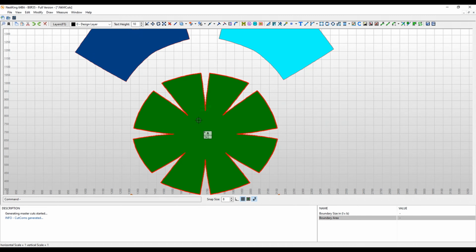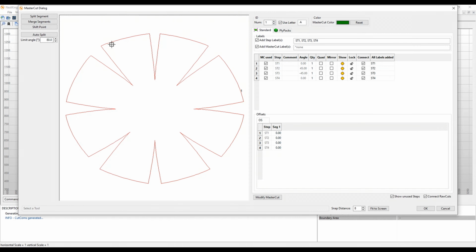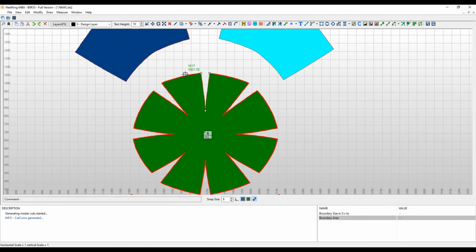part, the green one. Double click on it. We need to find segments. So I will split segments. I will use the split segment and split the outer curve into 3. So this segment and then the 2 ones here. Okay. Now when I hover with my mouse, I can highlight the outer curve and then the 2 inner ones.